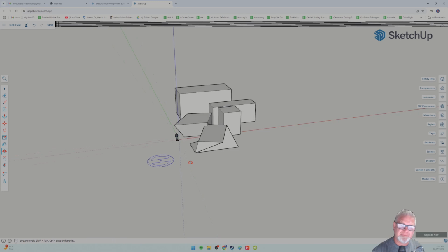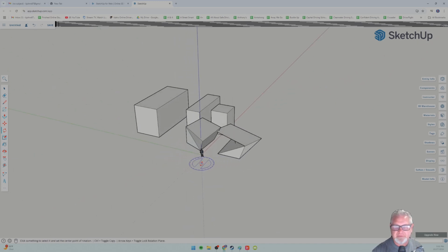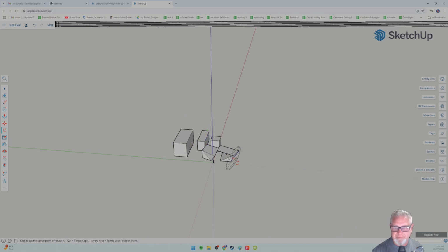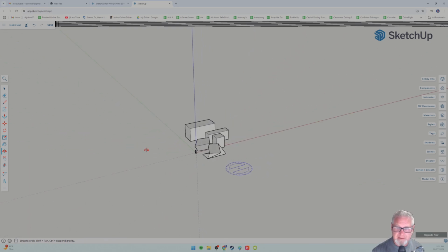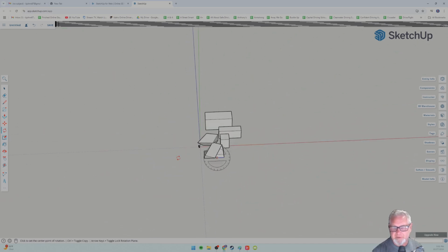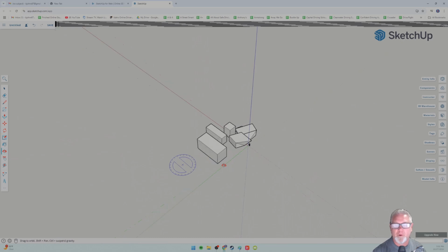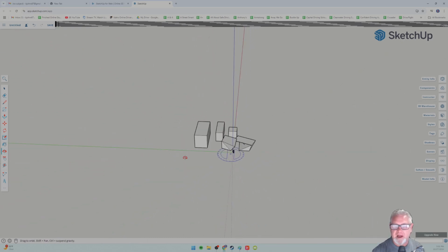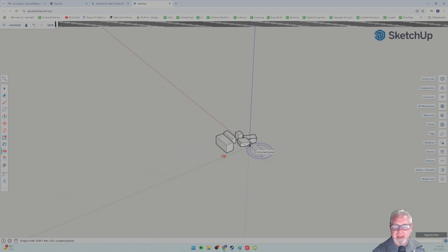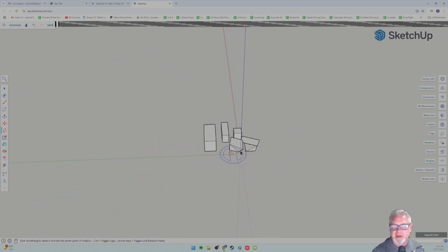All right, so you've been maybe struggling with how do you get around the screen. So let me just cover that. The mouse is so important that if I push down the mouse wheel, it is a button. Not sure if you knew that, but the mouse wheel is also a button. If you push down and then just rotate, that will help you. They call it orbit in SketchUp. So it helps you orbit. So I'm orbiting around. I use that all the time. Mouse wheel zoom in, zoom out. So orbit and zoom in, zoom out really, really helps.